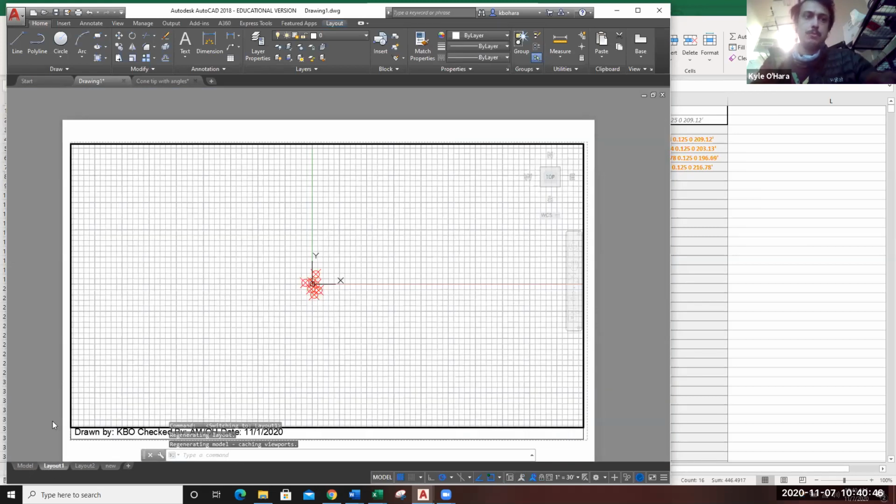You print things out in AutoCAD by coming over to layout. I've already made this adjustment in my default, but we're going to want these topos on 11 by 17 pages, and when you print to PDF they'll come out as 11 by 17, which changes the aspect ratio and makes it a lot easier to see.